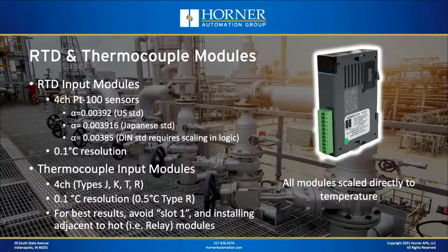However, if that thermocouple module is plugged into the first slot right next to the base, there is a power supply on the base that can get warm and can create hot spots. Also, if you have that thermocouple module plugged in next to, let's say, a relay output module that's driving some heavy loads, that could get warm as well.